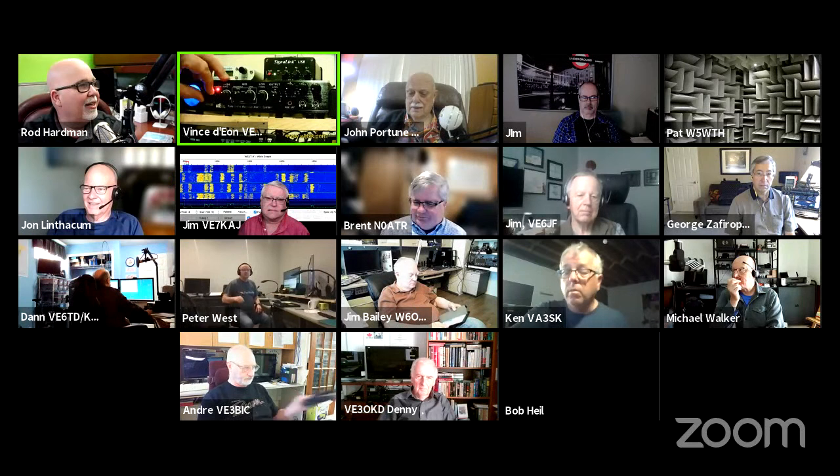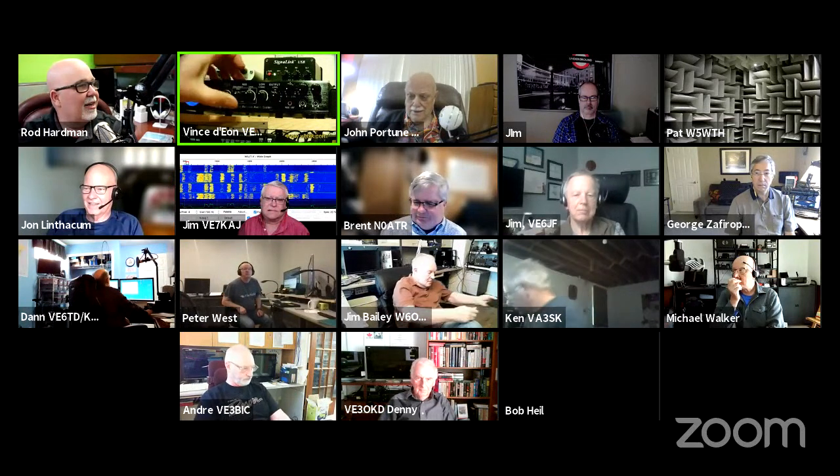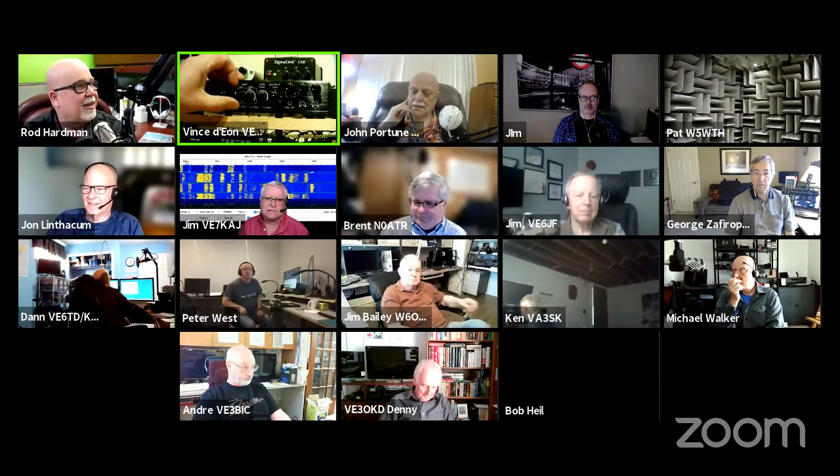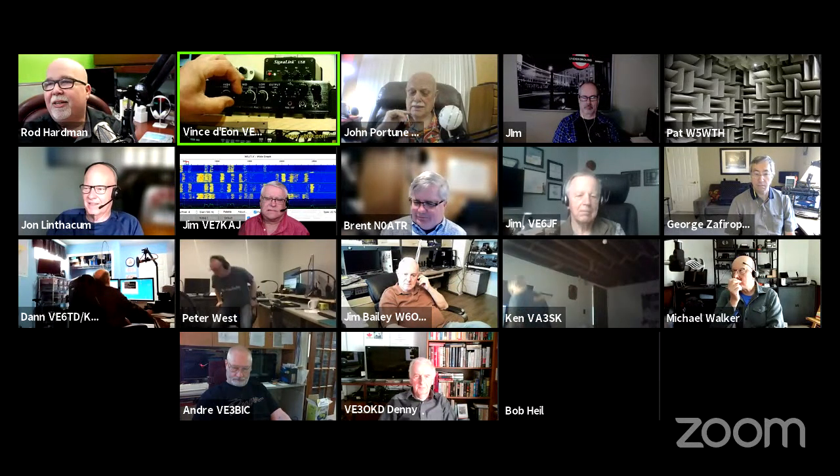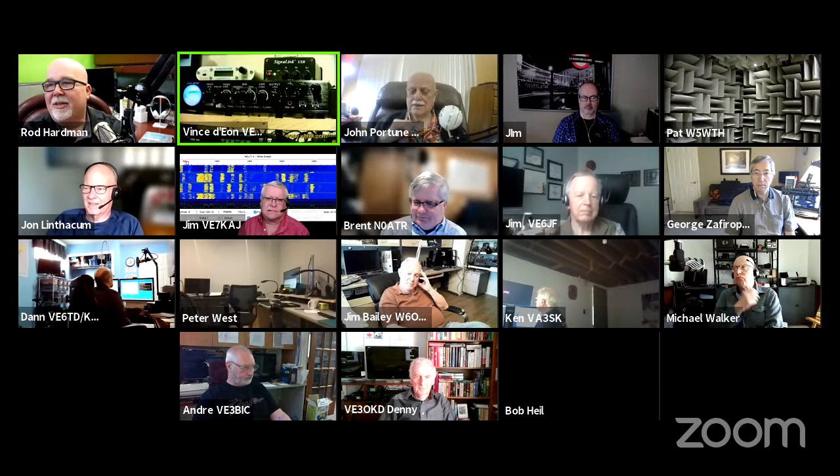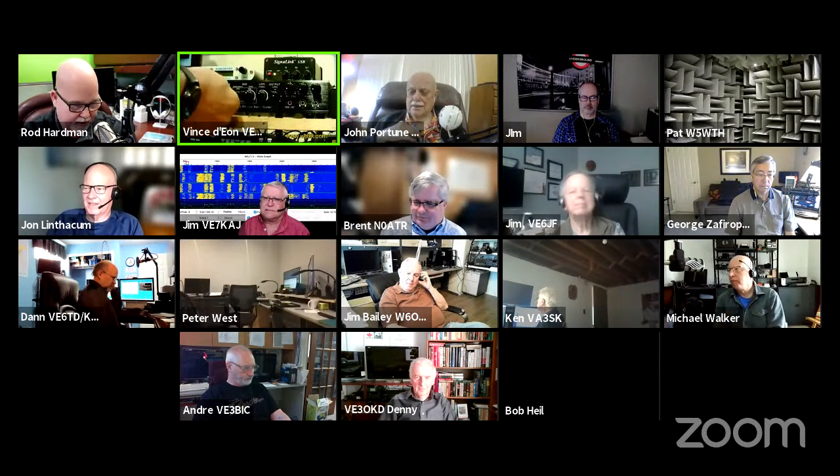All right, so not a lot of speech, and I'm clearly driving it a little bit too hot on the input, and you can hear that distortion on the output a little bit, but we can work with this at the top of the minute when a little bit of voice comes up. So if there's a little bit too much hiss in that signal for your liking, we can cut the high end drive from 0 dB backwards. I'm not sure what the sweep range is on the cut and boost knob on each one of these.